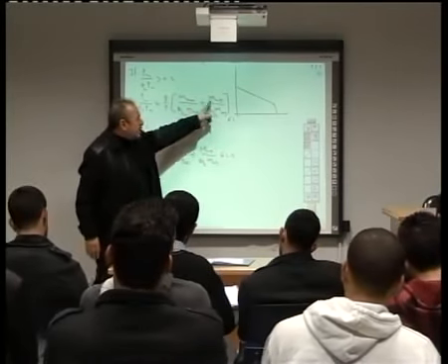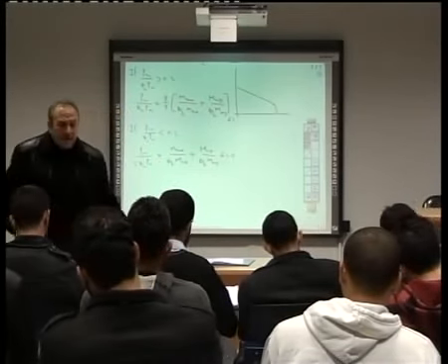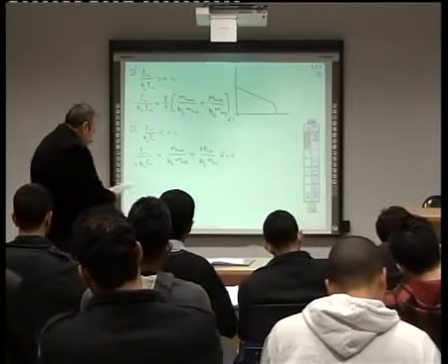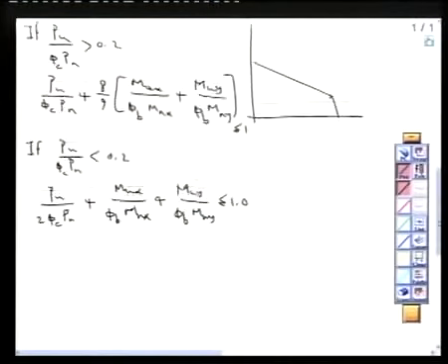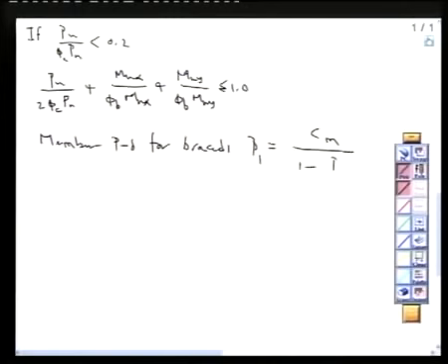M ultimate x and M ultimate y, if you got a braced structure, then they have to be magnified according to member B delta. And member B delta for braced is equal beta 1 equal Cm divided by 1 minus P ultimate divided by PE.